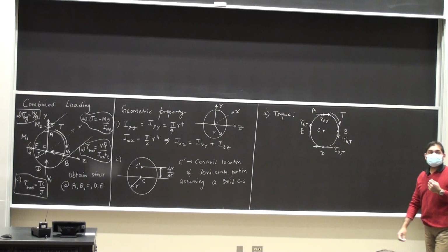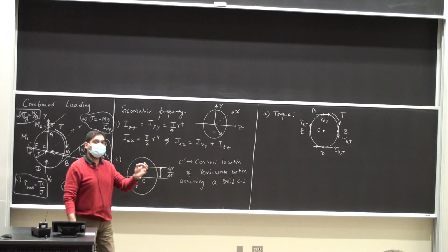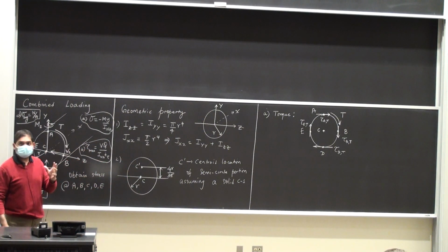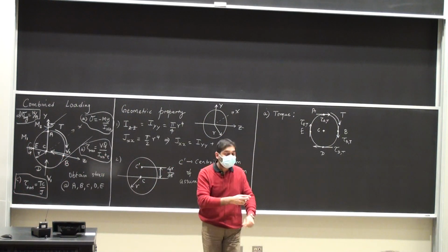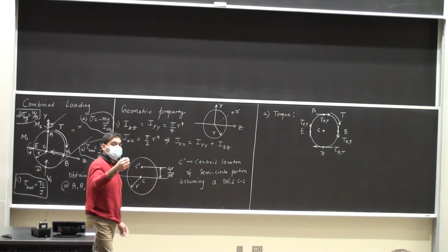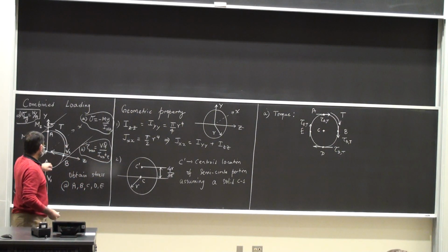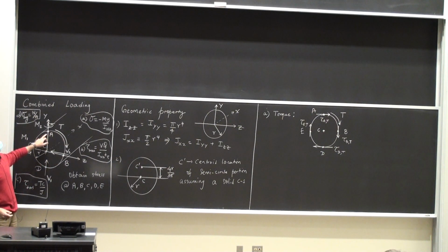What's the shear stress at point C due to the torque applied? Has to be 0, right? It starts from 0 and increases linearly as I go towards the outermost circumference of the cross section. Okay? Yes. No, that is the centroid. So centroid is the center of the cross section. The neutral axis will pass through the centroid. Okay? So in this problem, I can have either this axis as the neutral axis, or I can have that, and I'm going to talk about that. I can have either one of them as a neutral axis depending on which loading situation I'm looking at.